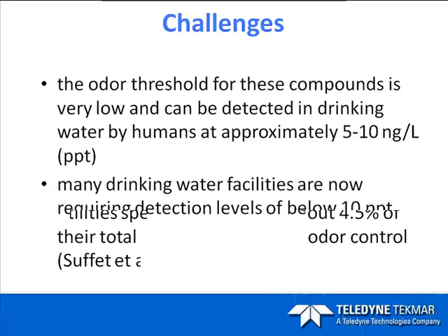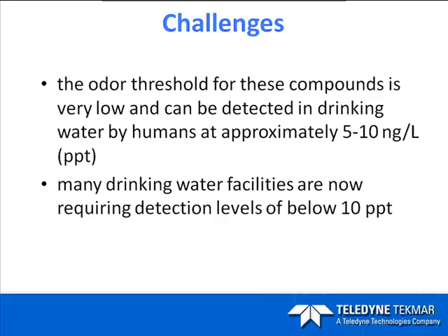Some of the challenges we face are that the odor threshold for these compounds is very, very low and can be detected in drinking waters by most of us at around 5 to 10 nanograms per liter, or 5 to 10 parts per trillion. Many drinking water facilities are now requiring detection levels of below 10 parts per trillion.